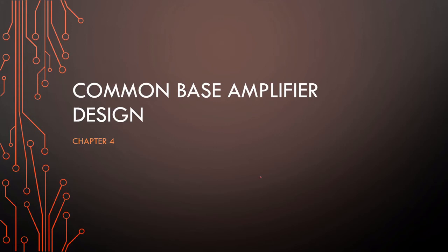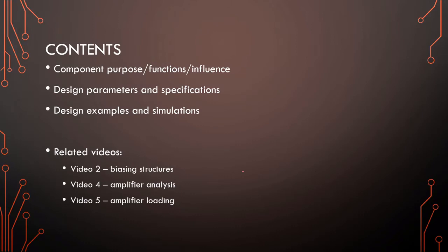Welcome to a video on common base amplifier design. Right, so the common base is one of those amplifiers that is very popular in high frequency applications because it has a very high bandwidth and a very small input impedance, which is typically required when dealing with antennas.